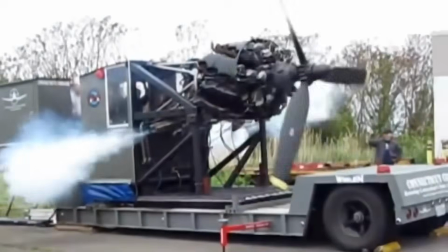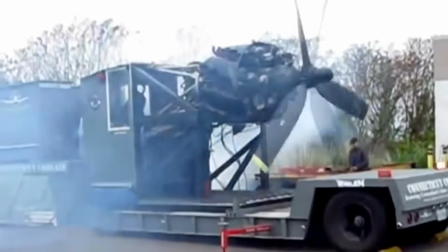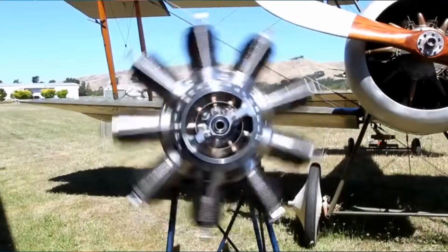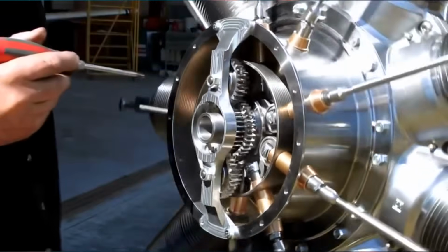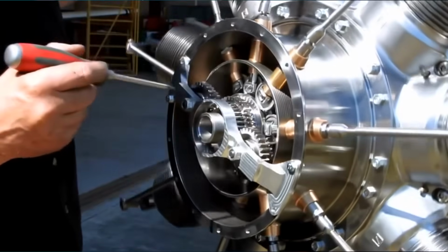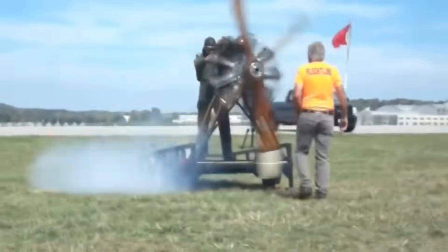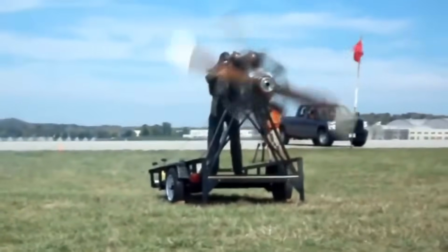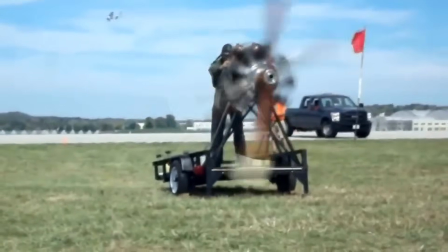The main disadvantage of the radial engine design is the possibility of oil leaking into the lower cylinders. The rotary engine design has several disadvantages, including higher loads on the crankcase from centrifugal forces, which means that the rotary engine has a structural limit determined by the strength of the alloys. Such a setup has a large gyroscopic moment, which negatively affects the handling of both the airplane and the motorcycle. High oil use results from difficulty pumping it from the rotating crankcase.